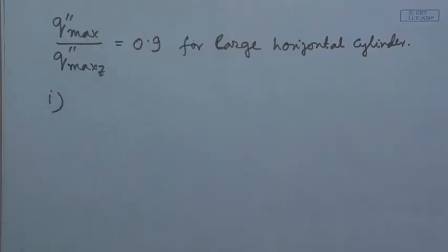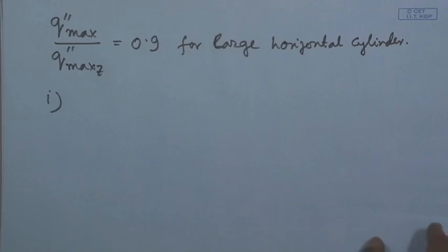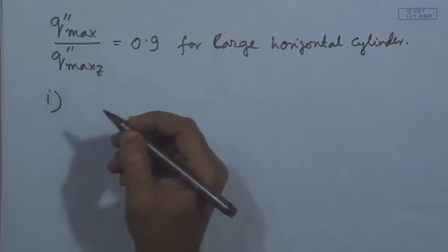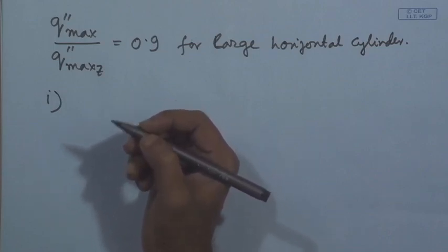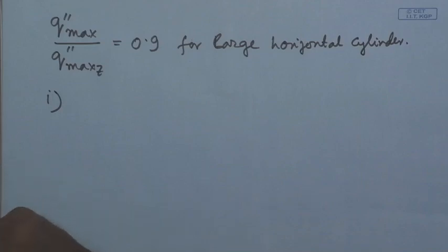Now, the hydrodynamic model of critical heat flux is not free from criticism or limitation. If we list down the criticisms, then it is like this. Firstly, critical heat flux is a phenomenon which culminates from nucleate boiling, but for predicting critical heat flux, we are proposing altogether a new phenomenology.